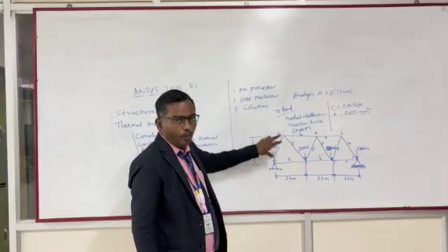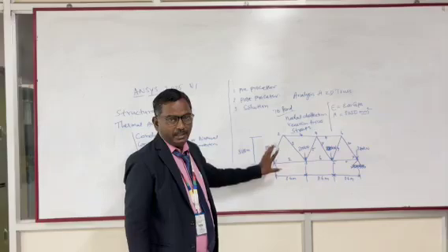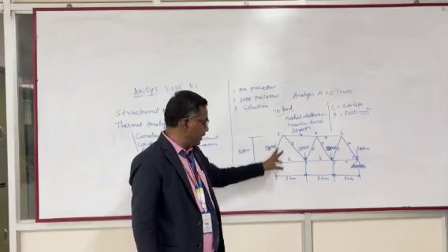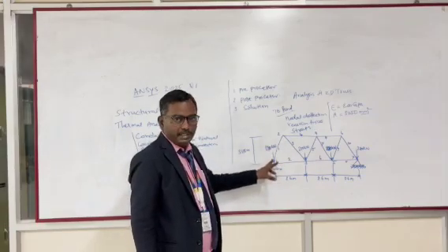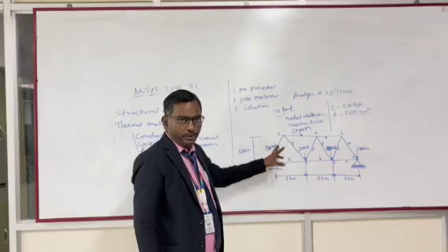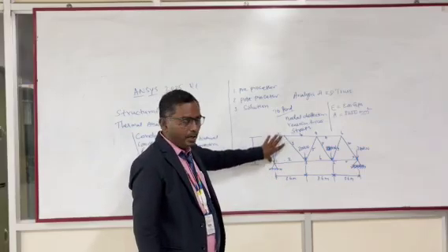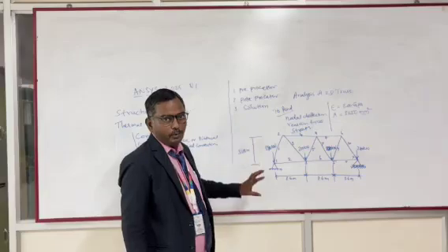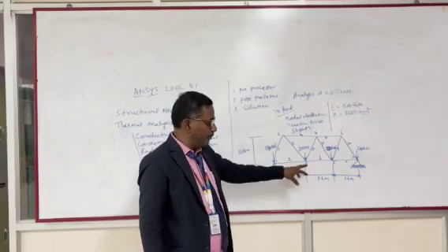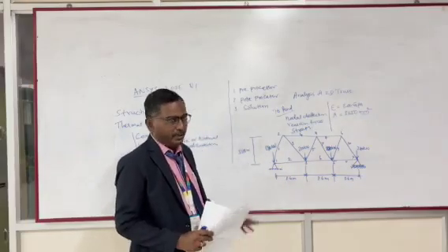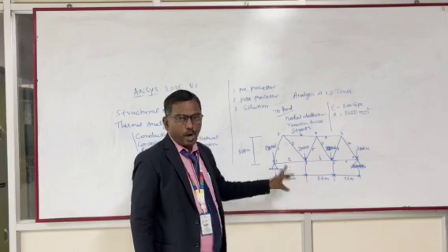Key point 1 to 2 is one truss, that is one element, so there is no need to divide 1 to 2. We need not divide the key point 1 to 2 distance into several parts. Okay. So we can take this as one element. So there are a total of 11 elements and 7 key points. Okay. These key points are used to draw the diagram.